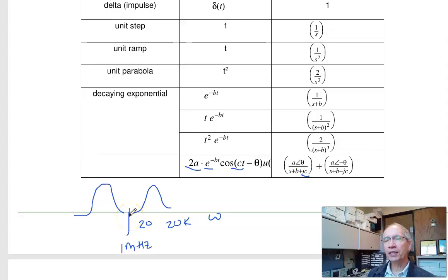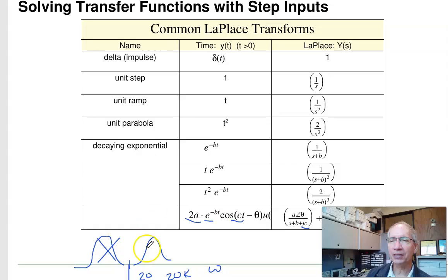Well, when I have a radio station, if I transmit this, this takes power, that takes power. If I could eliminate the lower sideband, I wouldn't lose any information, but I would cut the power demand by half for the radio station. It makes the math really ugly, because I now have a complex number without its complex conjugate. But if I can figure out the mathematics, I can cut the power consumption for radio stations by half. So that's one place that you see complex numbers without their complex conjugate, communication systems. That's upper sideband transmission. That's a different class. Almost every other class, you'll always have complex conjugates for any complex number, including this one.